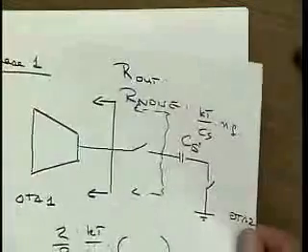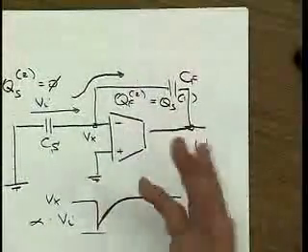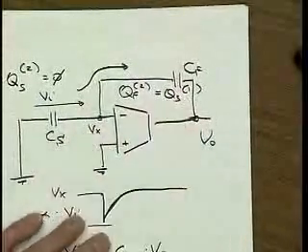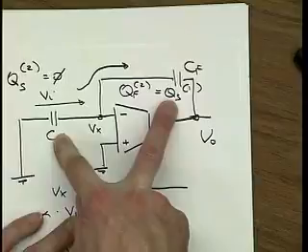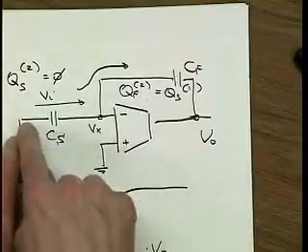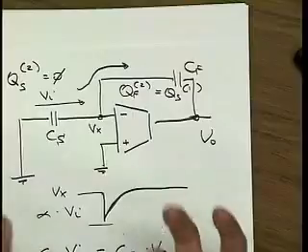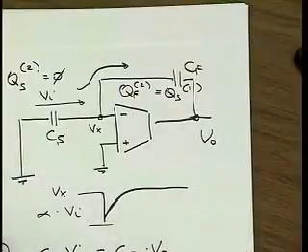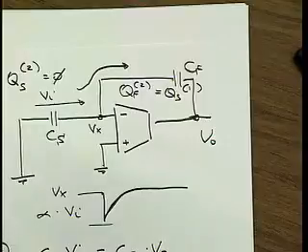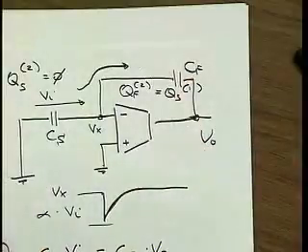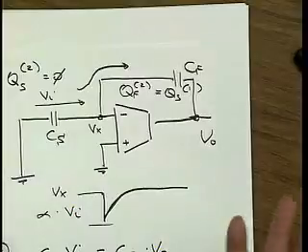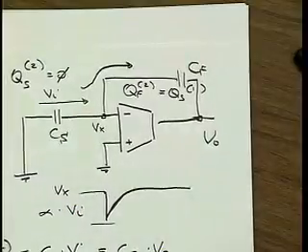All right. So apparently during phase 1 we are getting two noise samples that are just stored onto these capacitors. They have no other chance, because when the amplifier is really in business, it just pumps that. Once we've opened the switches, there is nothing random anymore. It is 20 microvolts, the noise sample, and it just sits there. We don't know ahead of time what it is, but once the switch is open, it's really a deterministic voltage, nothing particularly noisy about it.